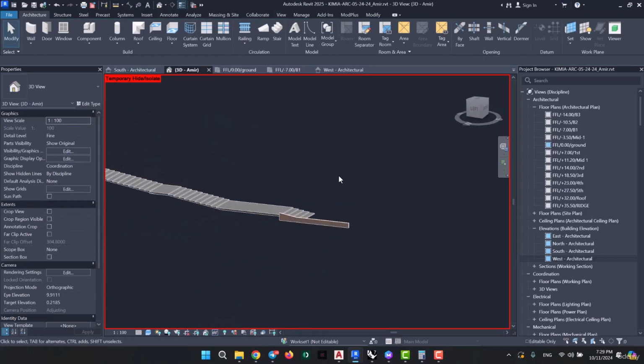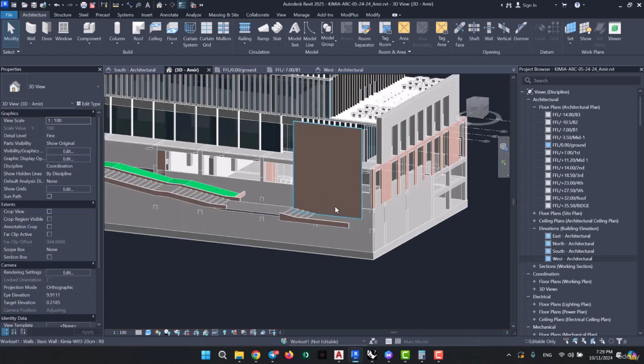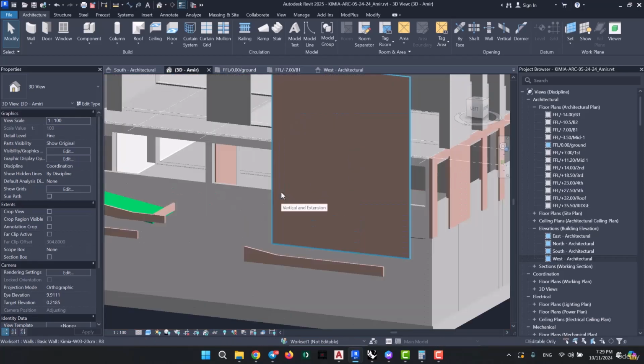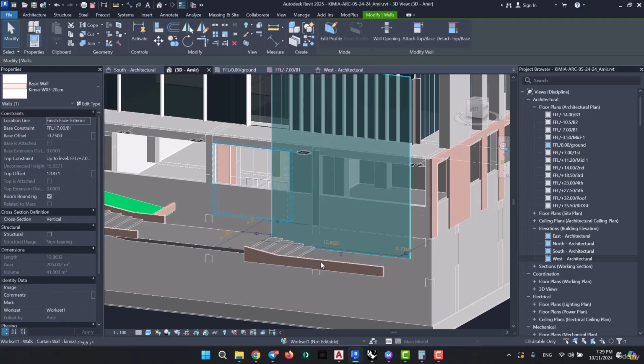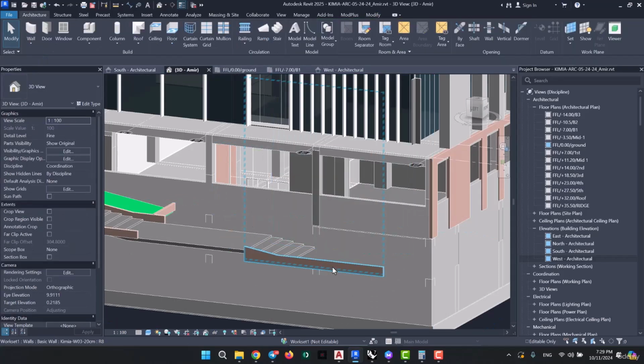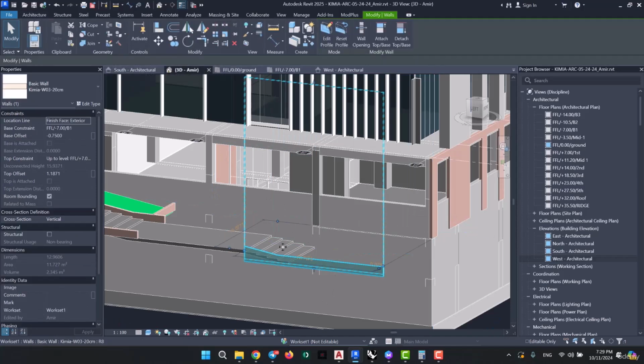And now for the other side, we could just put a straight up wall. As was the case in the actual project, we needed a whole wall here. But because we're not going to be drawing it in a way to lead to the other building, we could just make this wall with a slope, just like we did the other side. Either way, the actual project needed it to be straight. But instead, I'm going to select this one, then copy it.